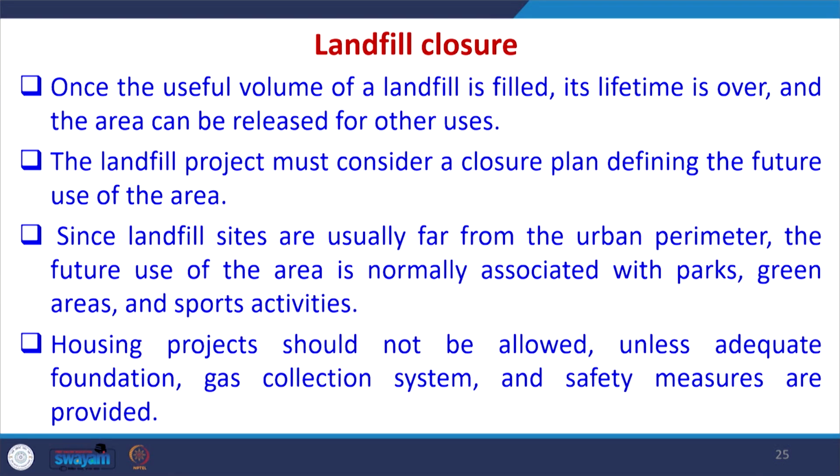Finally, after some time we have to go for landfill closure. Once the useful volume of a landfill is filled, its lifetime is over and the area can be released for other uses. So, the landfill project must consider a closure plan defining the future use of the area. Since landfill sites are usually far from the urban perimeter, the future use of the area is normally associated with parks, green areas and sports activities.